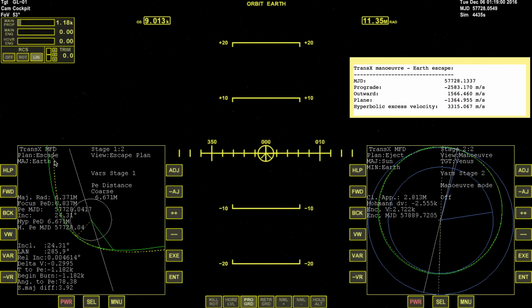So we can match the thrust by just putting in a bunch more power into the engines, but we have a difficulty now that our final trajectory is no longer aligned with the trajectory that we need to have in order to get to Venus. And this presents a problem. We have to make a further correction in order to sort this out. And you're basically looking at hundreds of meters per second in order to sort this out. And the whole thing is quite unsatisfactory.